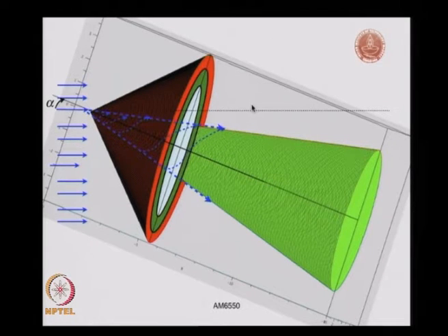About this, if you look, the shock wave angle varies as we make different phi angles. If I make a certain phi angle about the axis of this cone, then my shock wave angle will also change, which is not the case for the axisymmetric case that we did. So in this case the shock wave angle is also a function of the phi angle, isn't it. So we have a shock wave like this, right.